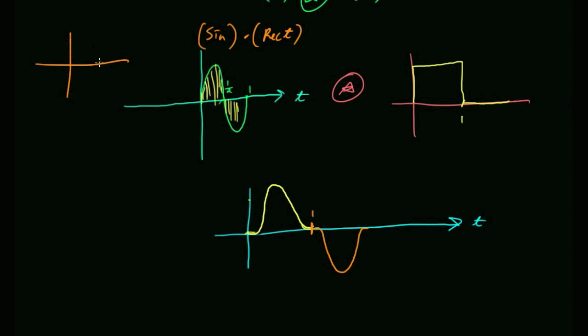Then you're convolving it with this other rectangle, which means that in frequency space, you're multiplying with a sinc pulse. So if you take this and do a pointwise multiplication with your sinc pulse, you'll get the Fourier transform of your final answer.